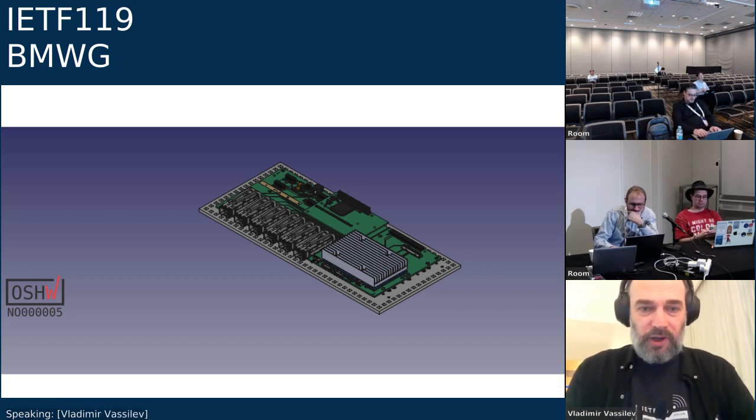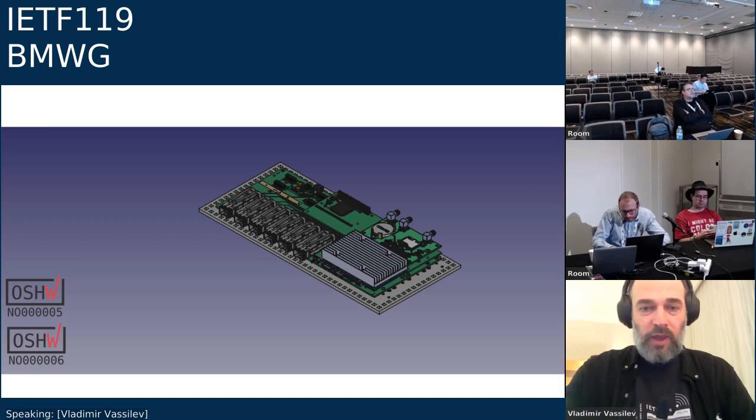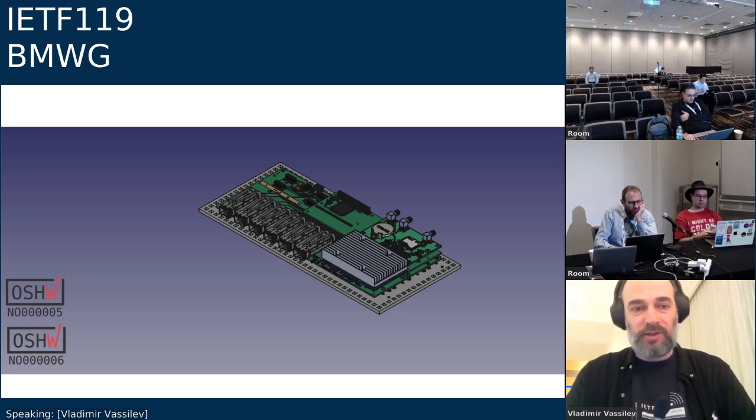Okay, so this is just a slide of the hardware platform, which we previously had as the only reference design. And if you go to the next two slides, they're just evolution of that. So this is adding a timing module, which is important because you can have a device under test that does not allow a loopback connection. So if you want to just measure one direction, then you need a precise timing. So we assume that the timing will be precise, and we have not put anything in the modules that has to do with configuring the timing. But we have this card which is providing a GPS synchronized oscillator and real-time clock. So assumingly the models are applicable to situations where the receiver and the sender, the generator and the analyzer, are disconnected, not the same device.